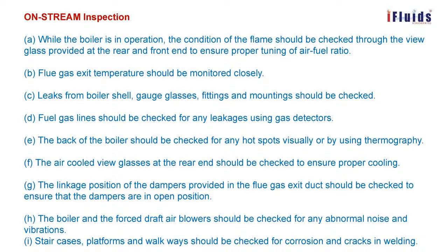The air-cooled view glasses at the rear end should be checked to ensure proper cooling. That is, in the view glass, one air line will be provided to cool that glass. If you want to see through the glass, the air line should be continuously blowing. Then only the area will be cooled.